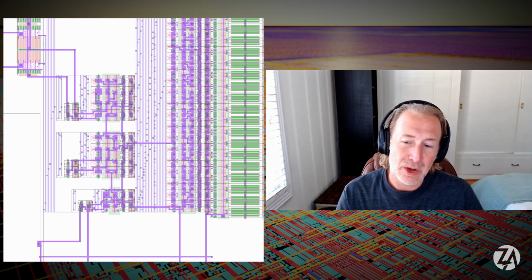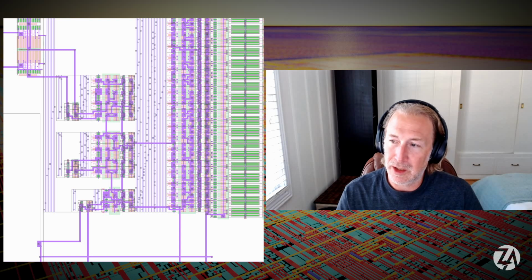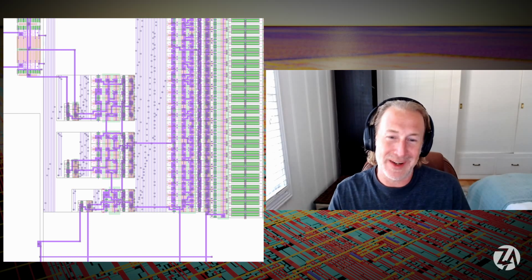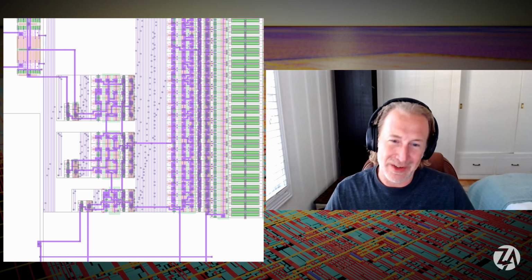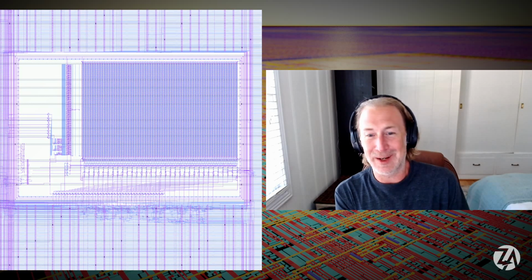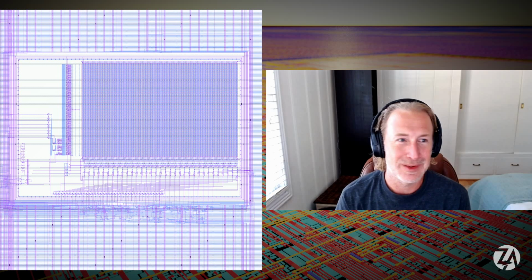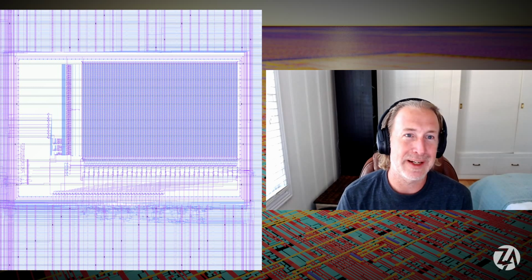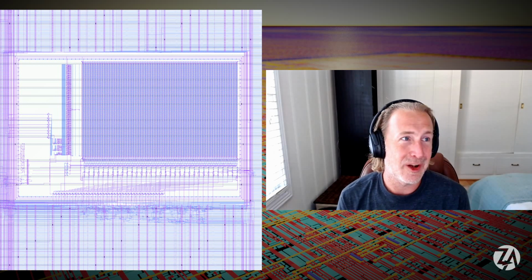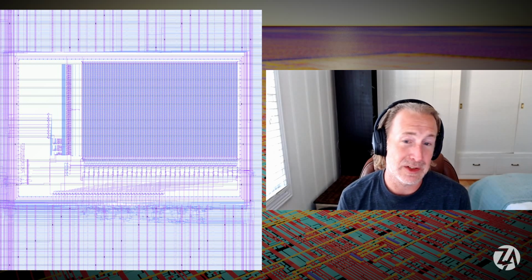The one limitation tends to be that you have to think about read and write ports. When you have a bunch of flip-flops, you can access any of them in parallel from different addresses, whereas with a memory you can only access one address at a time. So it's a little different from a bank of flip-flops. That's a limitation in terms of usage, but with the area savings, it's a big gain.